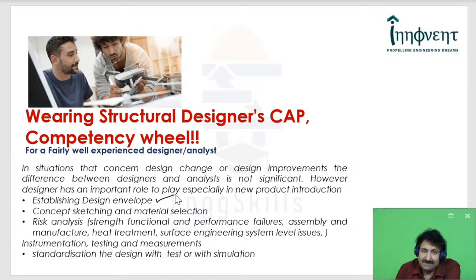And what exactly I mean by design envelope is the space occupied by your component during the worst operating condition. That means your neighbors may be growing thermally, they may be getting deflected mechanically, and they may be eating into your space, but you have to have no physical interaction with the surrounding components, and also maintain adequate clearances, which are very, very important from a performance perspective.